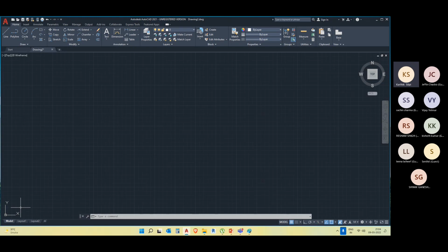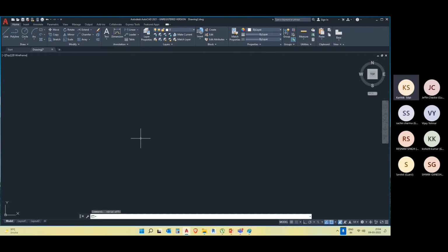So what limits is, this is an unlimited number of boxes. You can see when I scroll here, the boxes are grids. If I switch off this F7, it will be gone. If I switch on again, you have your grids. Grids are for reference. Whenever you print your drawing, this will not be visible. These are like grids in graph paper, you might have drawn in graph paper, right? But these are imaginary, for reference. As soon as I press F7, this will be gone.